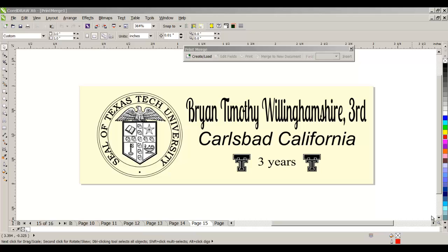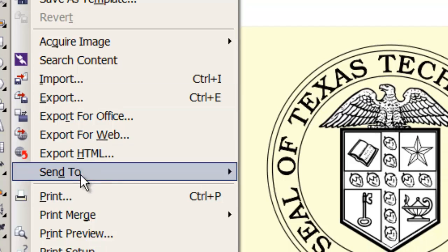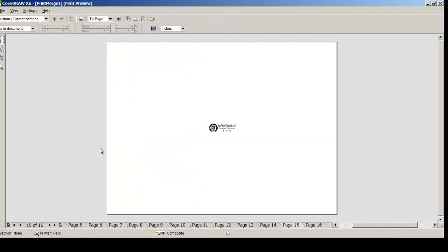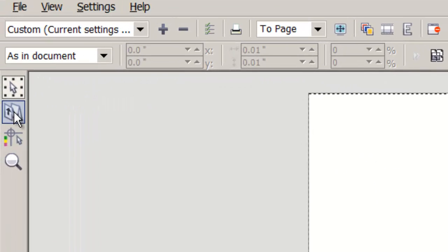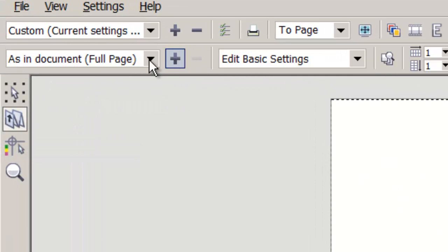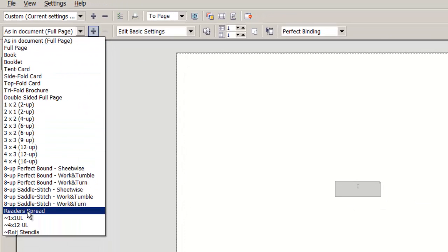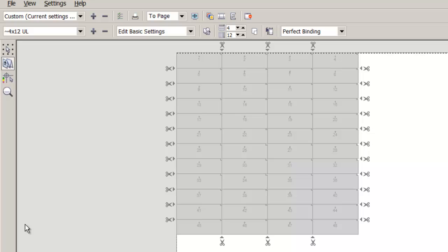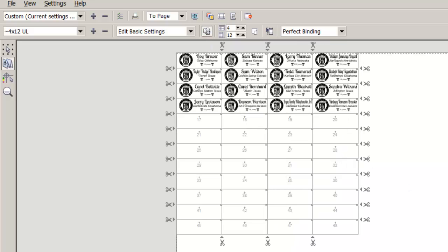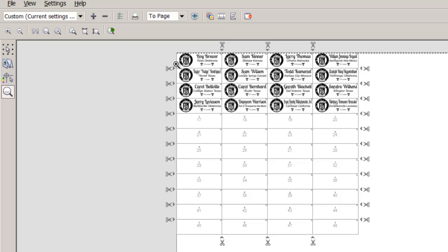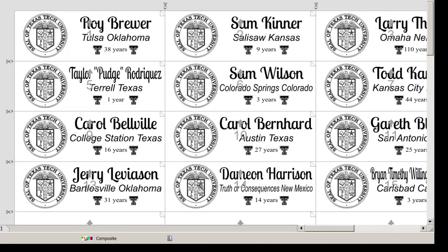So now let's assume this is destined to go to our laser engraver. So we'll click on Print. No, I didn't mean print. We'd be better off to go to File and Print Preview. And in Print Preview, we'd go to our imposition layout and select an imposition layout previously prepared, maybe 4 by 12. That's 4 across and 12 up and down. And let's have it show us that. Maybe we'll zoom in on a portion of that. And that's what we have.